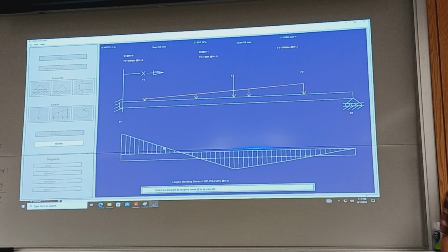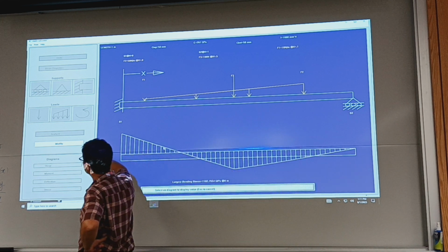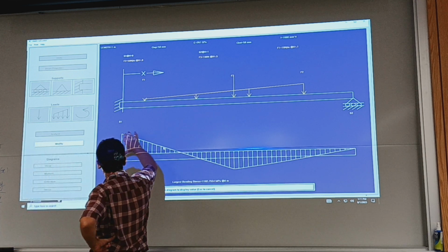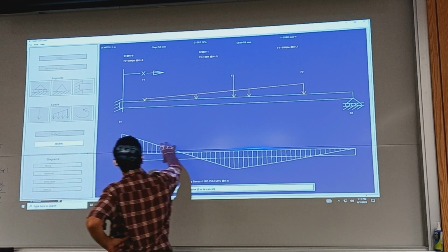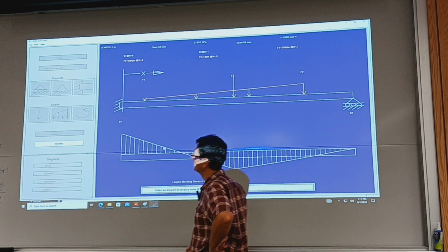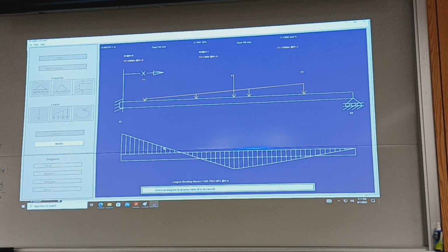We never created this kind of diagram, but since the area properties were given, you essentially use a figure similar to the moment diagram, multiplied by C over I or divided by S, the section modulus.